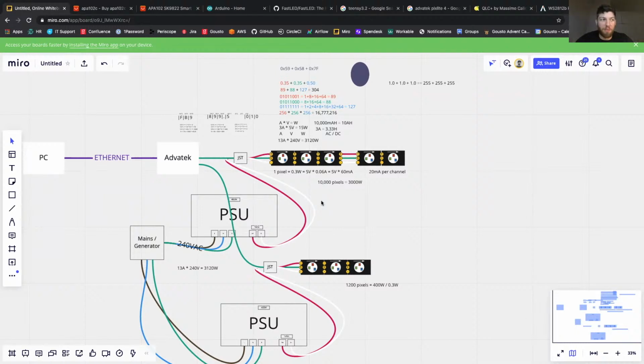I've seen and participated in some projects which were excellent in every regard other than their considerations for substructure. And I've been part of some horrific attempts to attach LEDs to materials that simply don't want to hold them. The glue strip that comes shipped on the back of these LED strips will not get you anywhere. That has never worked for anyone in any context. You need mechanical fixtures in order to hold LEDs permanently onto any sort of structure. So cable ties are very, very useful.